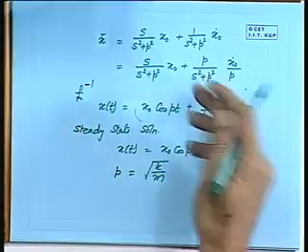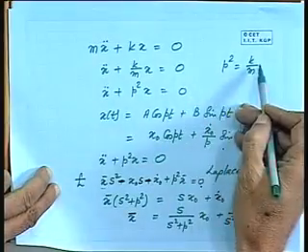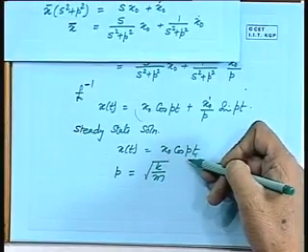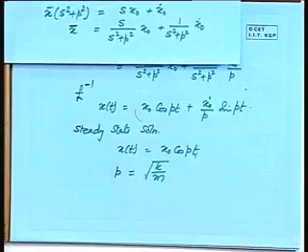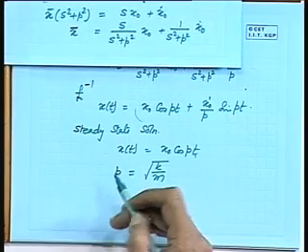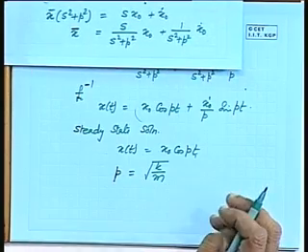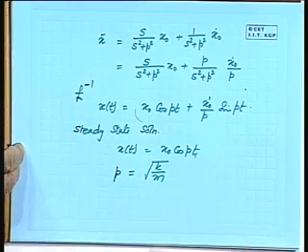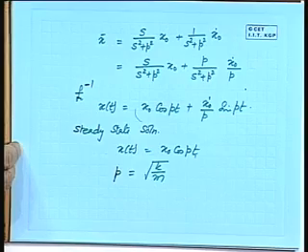We have assumed here that p square is equal to k by m, and what we get in this solution is p, the circular frequency. So, p is given by square root of k by m. Any other property can you think about from here? P will also be following a cos curve. Sine curve, you shift it by pi by 2, it will match with the cos curve.